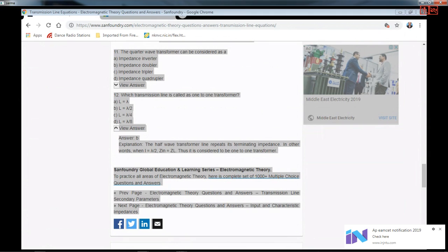And as you know, ratios in communication engineering are normally expressed in terms of the dB scale. If you want to convert this VSWR into dB scale, we take 20 log of S. Why is 20 log required? Because we are taking a voltage ratio, the maximum voltage to minimum voltage of a standing wave, which is what we consider for VSWR. So it is 20 log capital S that has to be taken into account.